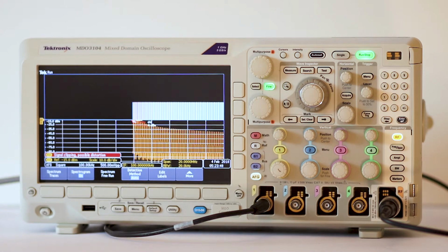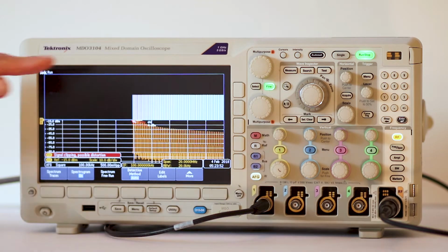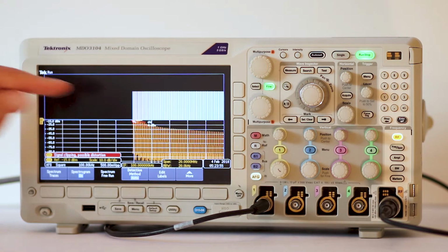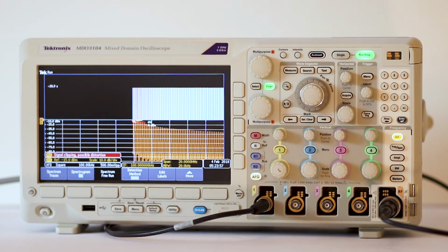Here, in split screen format, is the standard frequency domain in the lower display and the spectrogram at the top. Notice that the display starts at the bottom and slowly moves to the top. You might think that it is taking time to load, but that is not what is happening. Actually, for a spectrogram, frequency is plotted along the x-axis, as in the frequency domain, but time is plotted along the y-axis. If we toggle the spectrogram off and on, it starts over.